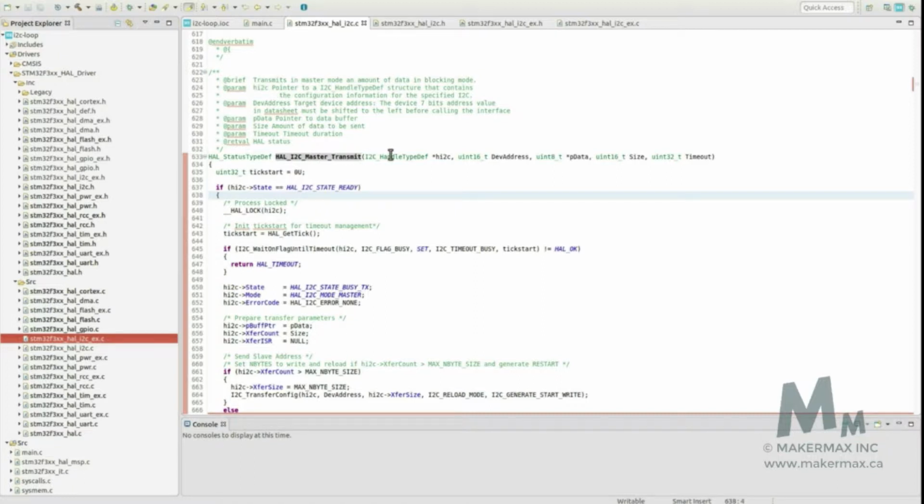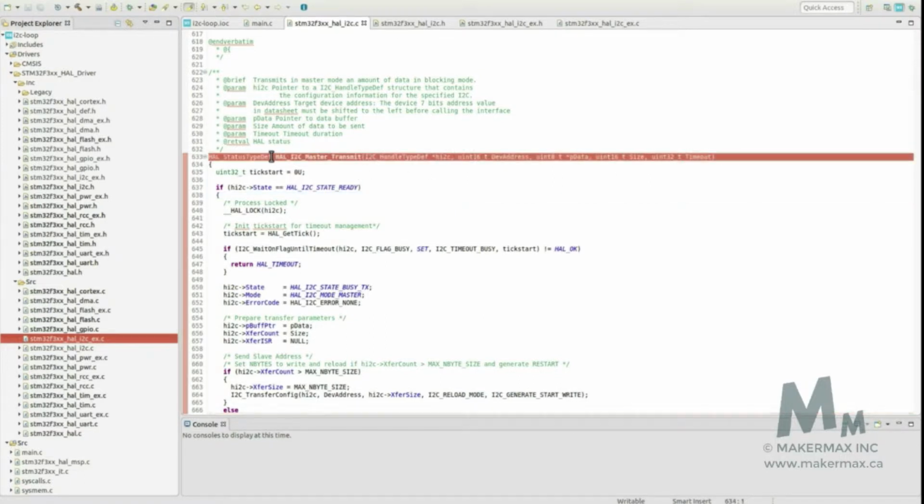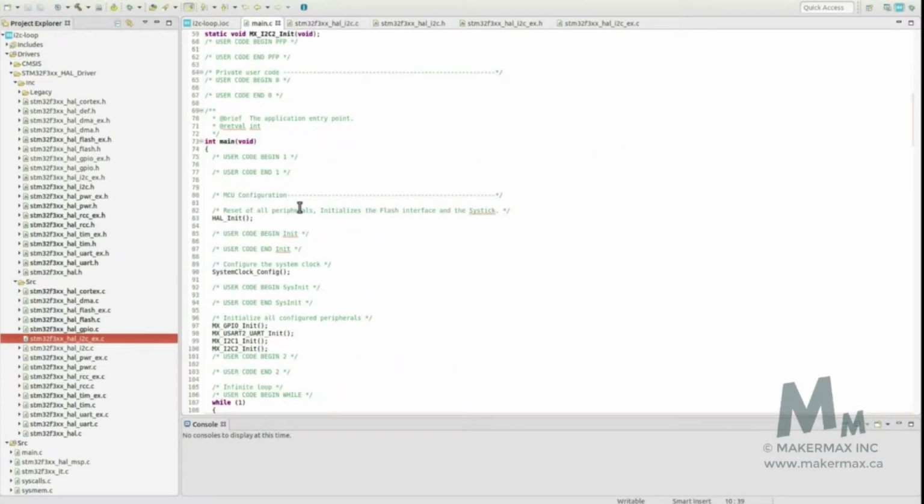That is interesting. So that is going to block, and let's see if this is going to work, because if it's going to block, I wonder if the slave, because it's the same processor that's running both of them, and if the master transmit blocks the processor won't have resources to read from the slave, which is both connected to the same processor. So let's see if this works. I hope it does. We're going to copy this onto the main.c file.